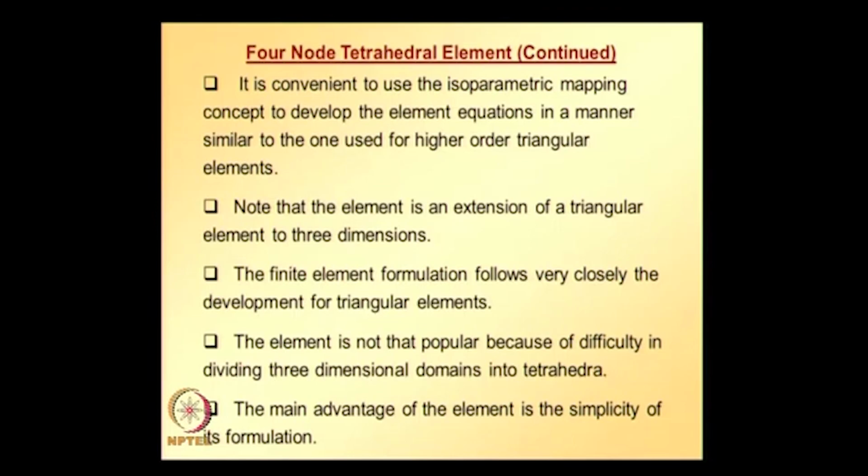So, we start with a polynomial having number of coefficients equal to the number of nodes of the particular element, and by substituting the trial solution values at the nodes, we solve for the coefficients and substitute back these coefficients into the trial solution and group terms having similar coefficients which correspond to the nodal values, and then we are going to arrive at finite element shape functions.